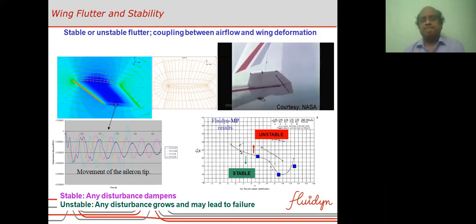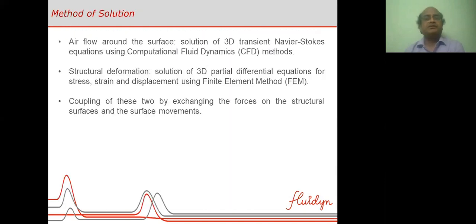So here we need to model the airflow around the surface. That is done by solving three-dimensional Navier-Stokes equations using CFD methods like finite volume methods. And the structural deformation also is solved using an appropriate method of your choice. And these are coupled by exchanging the forces on the structural surfaces and the surface movements.